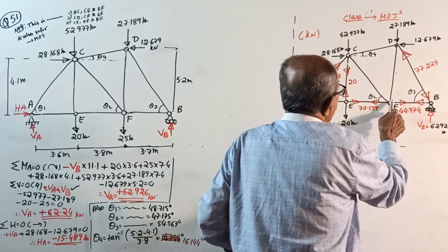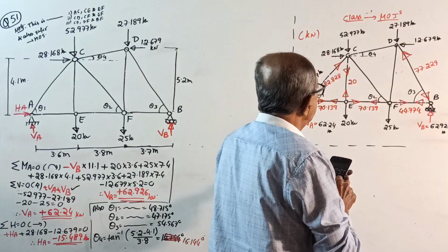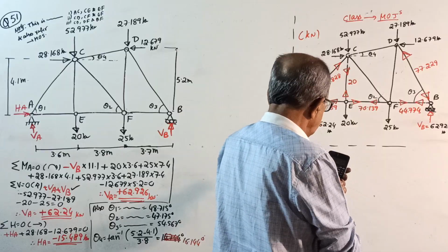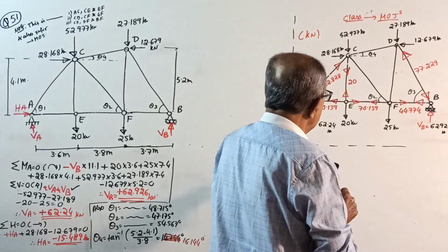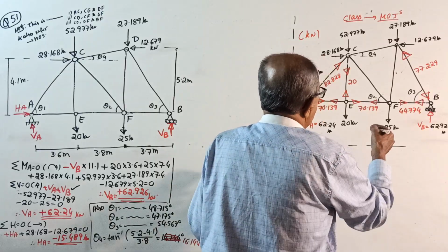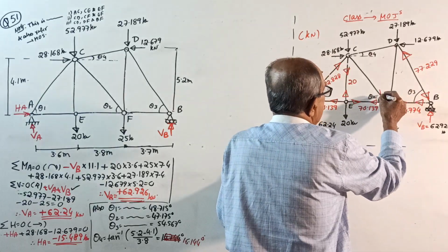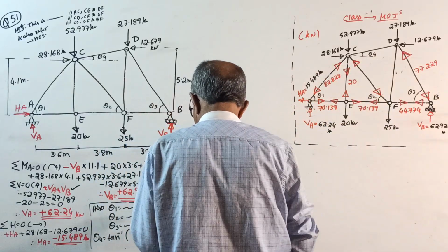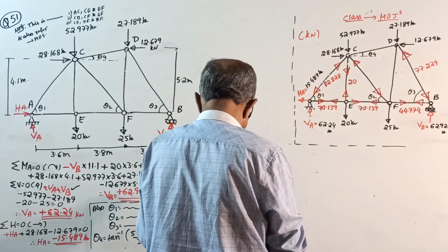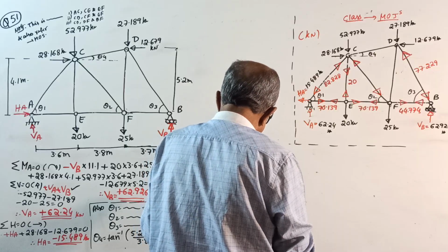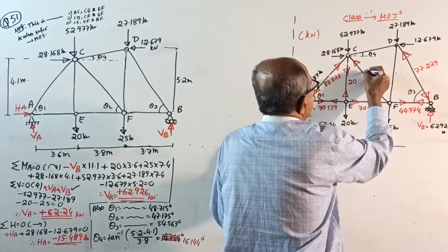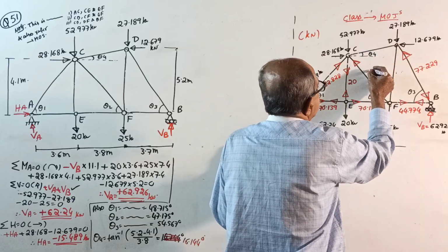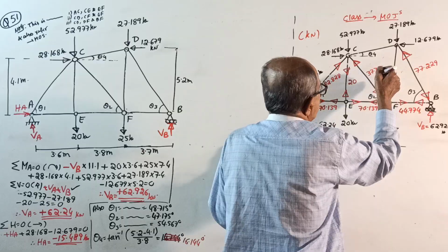Next for me, this joint is better. That is much easier. Okay. 70.139 minus 44.774, the net unbalance I got, divided by cos of this side. So this is this way, guaranteed this way, divided by cos of theta 2. Where is theta 2? 47.175. That gives 37.315. 37.315 is this force. Let me check once again.